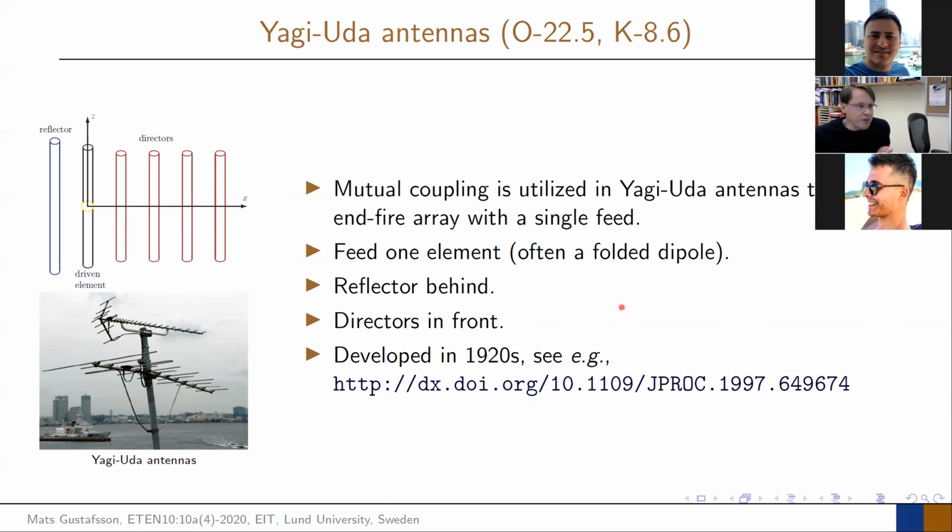Why do we use more than 3 elements in the Yagi? You mean more directors in some ways? So what you can see here is that this has quite a few directors. So there are many elements. I do believe also these are multi-resonant, so there are actually 2 Yagi-Udas inside of it. So what you do is to increase the directivity more.